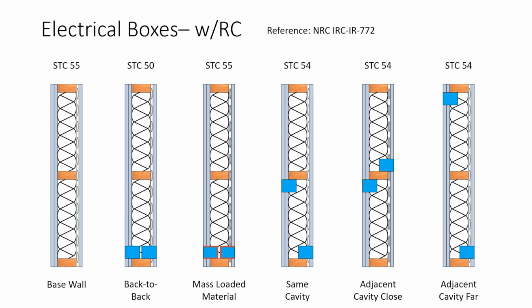And so if there's any other construction variation or anything else with this wall, which surely there will be, you probably now have that STC rating down below code. So just those two little electrical boxes are a significant liability in the acoustical performance of this wall. So we need to do something to bring this wall back to where it was. But we still obviously have to have the electrical outlets in it. People have got to be able to plug stuff in.